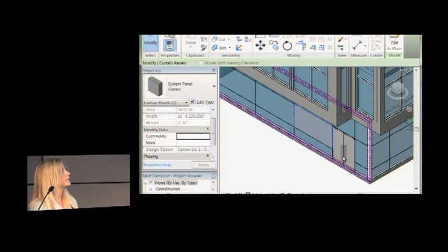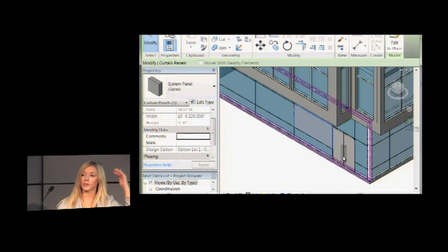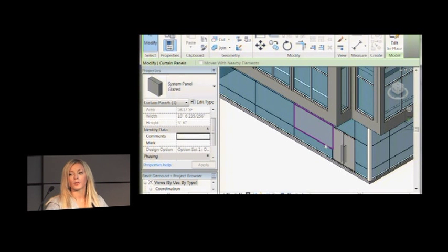So we do recommend that if you have a curtain wall, if you can, go all the way from the bottom floor to the top floor, choosing your opaque panels to represent solid walls rather than stacking. But that is a hard one with architects, because that is a very common way of doing it, especially for cutting through with your constructions, because obviously this wall would not just be a panel in a curtain wall. It might be a steel frame wall with more detail to it. So that is one of the issues with it.